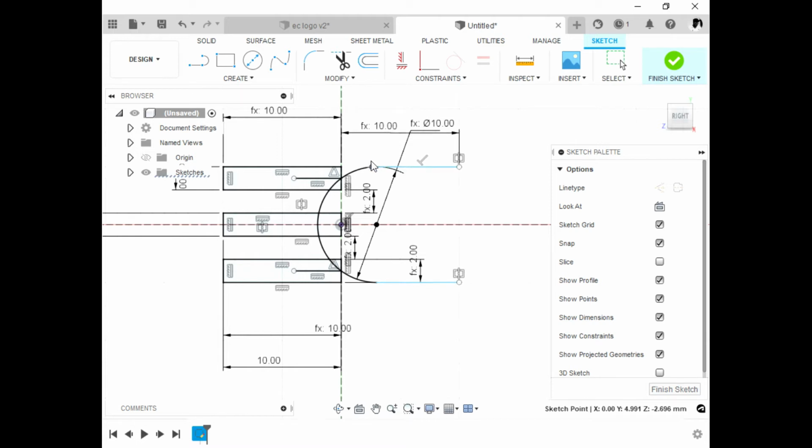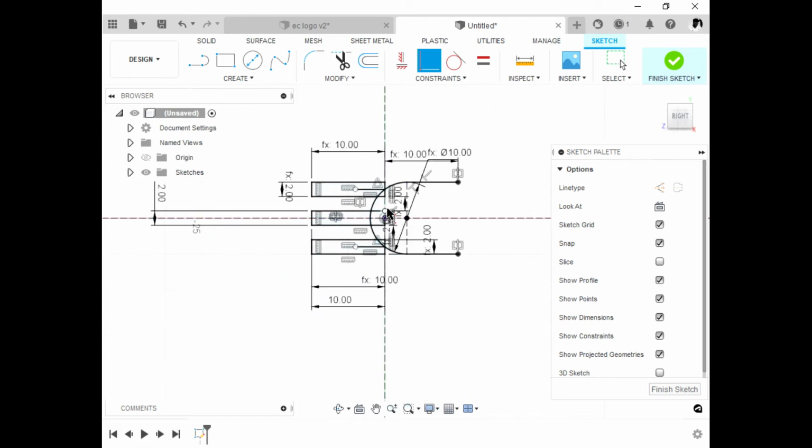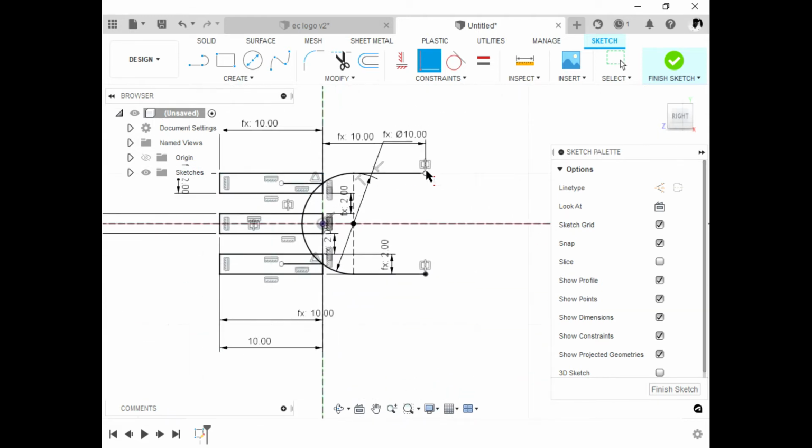So what I can do is add one line through the center, cutting the circle into half, into two semicircles. You ensure it is 90 degrees from the center there. See, it is dark now. I also make it a line which is not part of our sketch by just selecting the line and pressing X on your keyboard. That's when you're working with Fusion, like me.